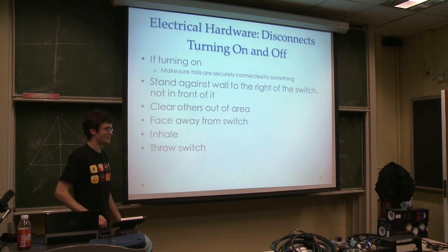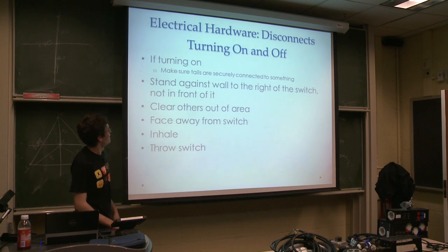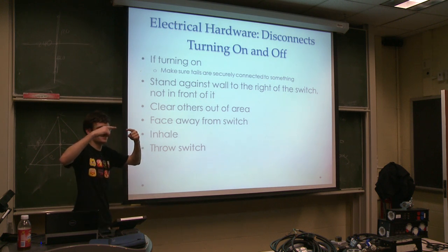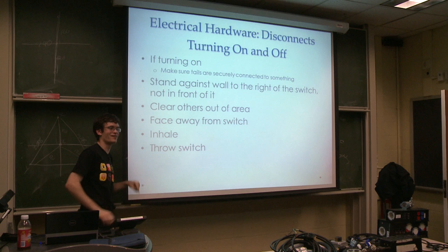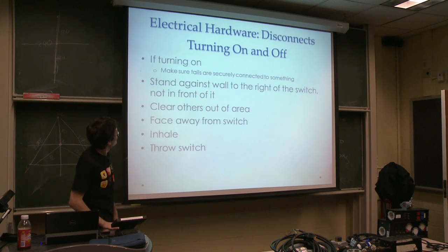So if you see that, you just turn things off. Yeah. If you see a loose camlock that's floating in space, turn it off. Plug it in. Just plug it in. Yeah. Because then you have a lot of current that wants to flow and a very weak connection. And when you get close enough, instead of waiting for the connection to happen, it'll just go across the air and explode. Weld the connectors together. Or that. Oh, whoops.